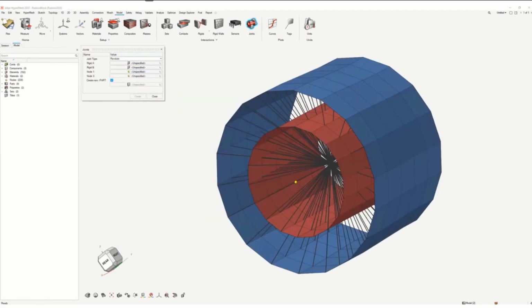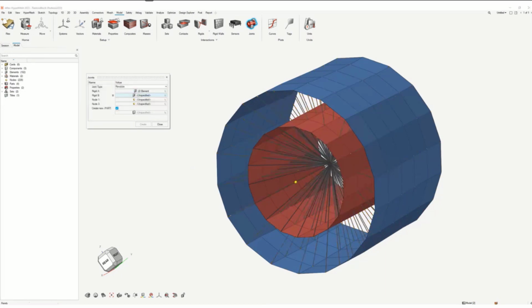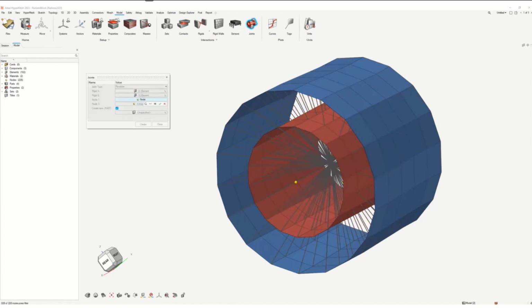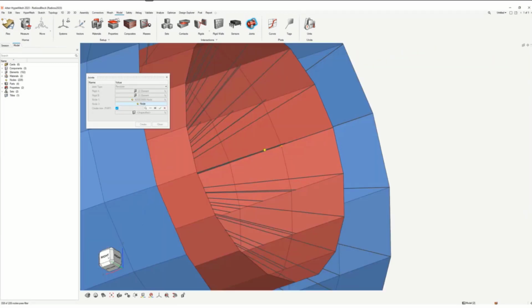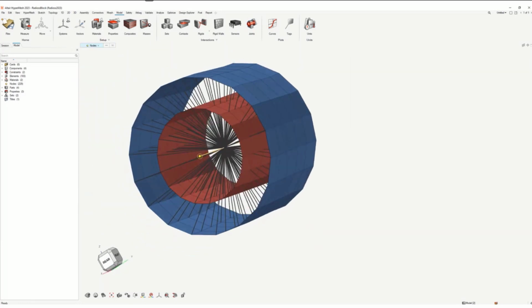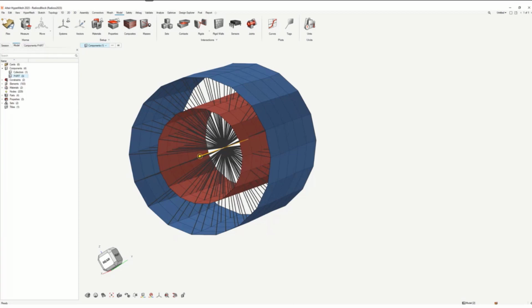As I mentioned, the joints creation is completely automated now. You just need to select rigid A and rigid B, of course first the joint type that you want to create, and select the nodes which are mandatory for the creation of this type of joint. At the end, the joint will be automatically created with the spring elements, the rigid connection with a merged rbody, and the corresponding property, prop K-joint2.